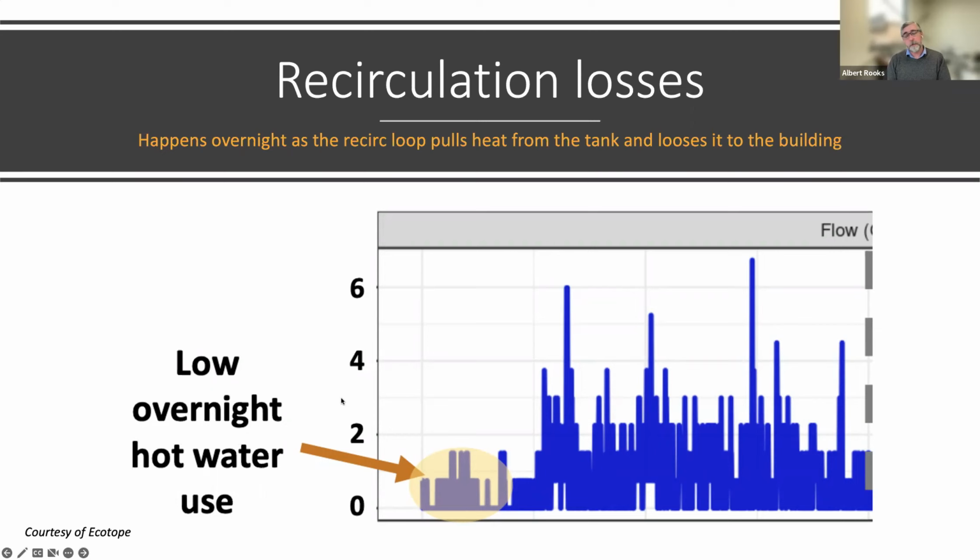Once we lose stratification, we lose that cold water splash at the bottom. The heat pump starts seeing warm water, and the system starts losing its performance characteristic. And that great 4 or 5 COP will start falling back down to 1 or 1.5 or something like that. It's always going to stay above 1, but it's not going to hit the numbers that we really want.